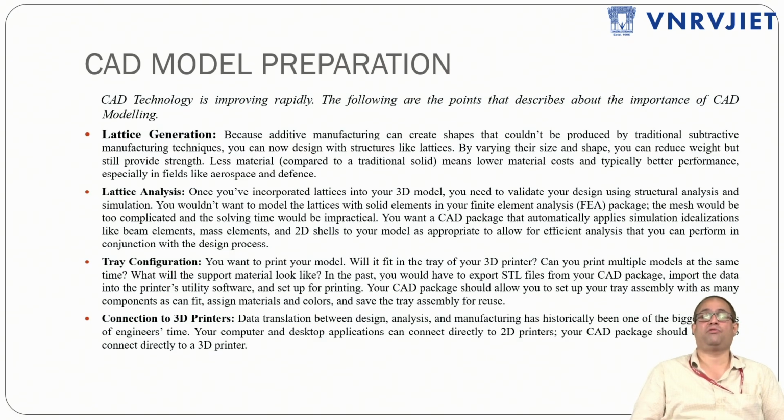How well your lattice generation is done, and how are you going to validate the structures you generate? These structures are evaluated using several FEA software, where the mesh and the complex profiles are meshed, and the CAD package applies the simulation with the help of beam elements, mass elements and 2D shell models, to analyze the entire lattice model we have made.